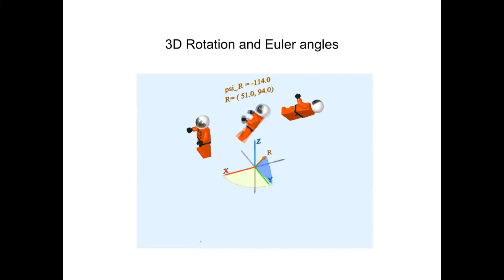So whenever you have a rotation, you can represent this rotation by three standard rotations. One rotation around the z-axis, one rotation around the y-axis, and the third rotation around the z-axis again. Actually, there are many different combinations of rotation axes for these Euler angles, but these are the typical ones that are used in quantum mechanics and that we also use, and that turned out to be very useful here. So whenever you have an initial orientation, an initial coordinate system or initial object, here it's a LEGO character, a little astronaut.